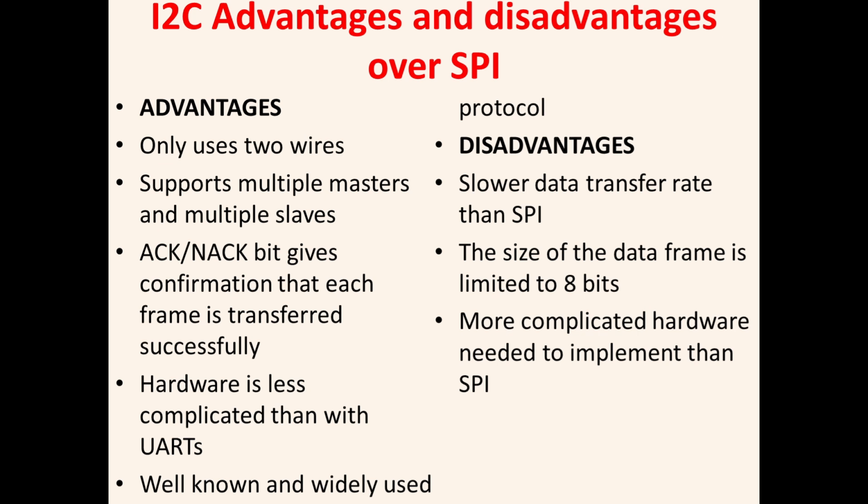So here there is no complication, only pull-up resistors are required for them. If you are connecting multiple slaves to your master, then and only then is a pull-up resistor associated with these two lines, SDA and SCLK.